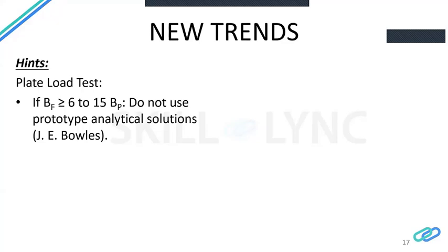The prototype analytical solutions provided in the books or the codes or in the manuals are not applicable for certain cases. If your width or size of the foundation is 6 to 15 times more than the plate, even if you have a homogeneous soil, it is not applicable to be used directly.